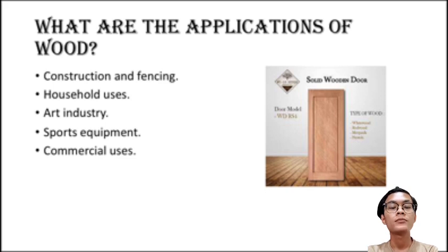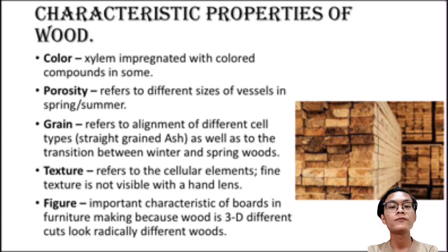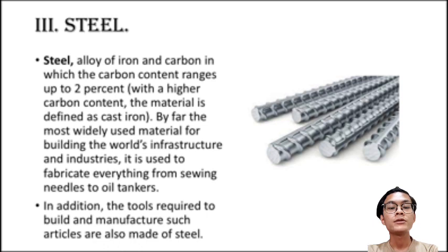Wood. Wood as a foundation material may look unsuitable, but it is used for house foundations in many cases where a concrete foundation becomes an expensive option. When wood is used as the foundation, it is pressure treated and coated with multiple chemicals to prevent rotting and to keep wood-eating pests such as termites away.